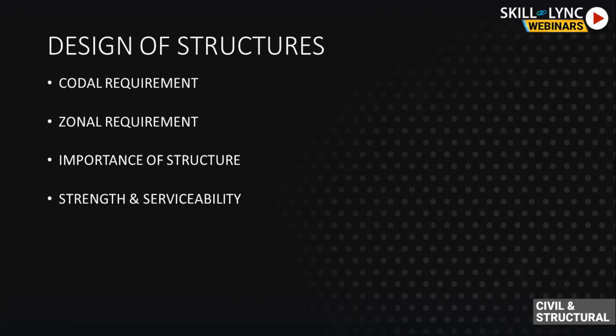That's what we call an unserviceable condition. So serviceability is also a very important aspect of the design. Generally, for design of structures, we determine the deflection of a structure from the serviceability limits. There are safety factors also for some important structures. We have different safety factors for different codes.